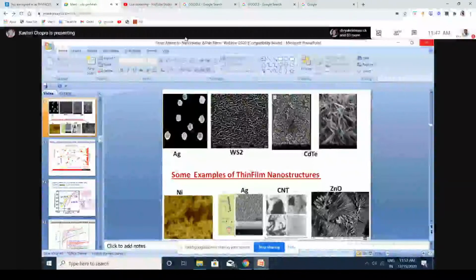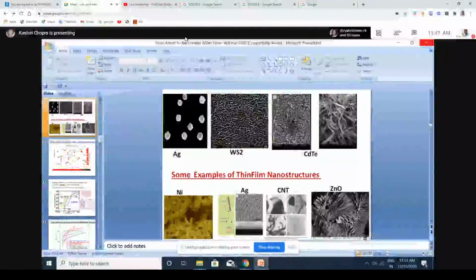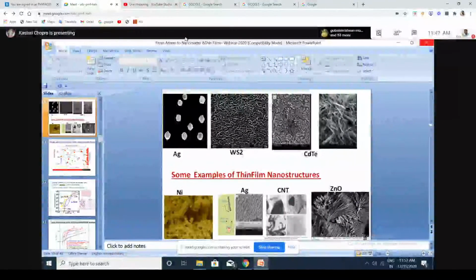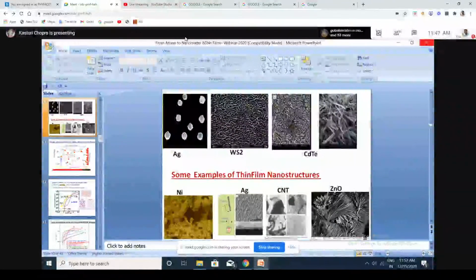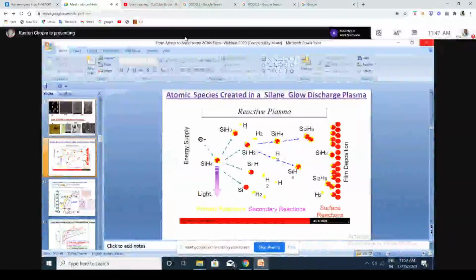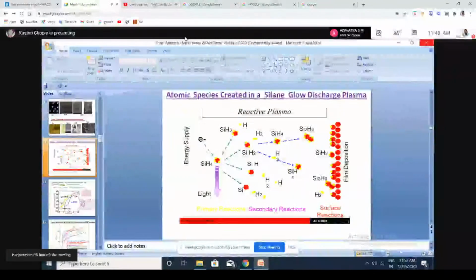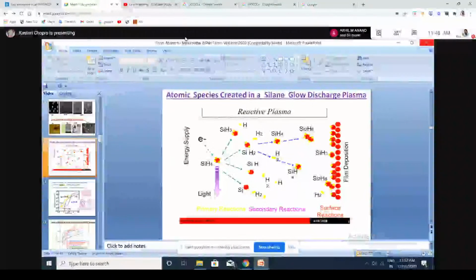So people who work with thin films are generally young people, not taught properly. They think that everything, when you put it down, is a flat, nice thin film. It is not. It could be any one of these structures. This is to emphasize again, because this is one area which I think for almost 15, 20 years the whole world was absorbed in. People naturally wanted silicon films. And silicon film means they took silane, for example, SiH4, and put it in a plasma.